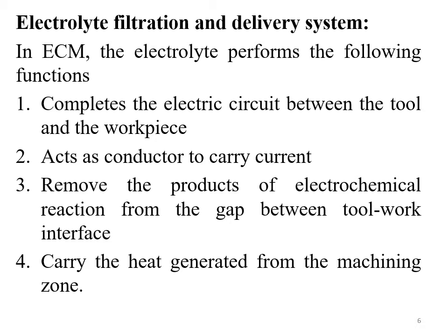Further, another important point is about heat generated from the machining. Obviously there is a chemical reaction, so we can say that there is a liberation of heat energy also. And the second thing is the metal ions are getting dissolved from their parent metal surface, and dissolving into the electrolyte. So obviously these are also some chemical reactions, and since everything is connected in an electric circuit, the movement of electrons will also cause the generation of heat energy.